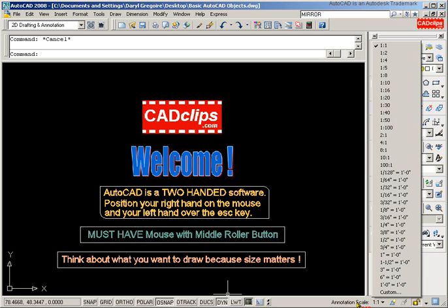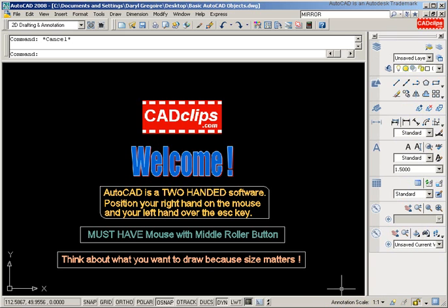And this sets the scale for the annotation objects. You don't set a scale for the model objects, the actual line work that you use to create the model. You don't scale, but the text and the dimensions and the annotation, cross-hatching, etc. I will teach you how to distinguish between what is an annotation object and what is not. This will control the scale of your annotation. So that is worth the upgrade to AutoCAD 2008 with that one improvement alone.